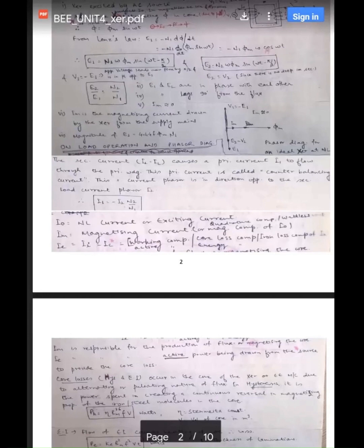Okay, so we can say that the secondary current I2 is equal to I load IL, or the load current. It causes the primary current I1 to flow through the primary winding, and this primary current was flowing due to the presence of the load, so it is the counterbalancing current. So number of turns are given to us, so N1 I1 is minus N2 I2. Okay,